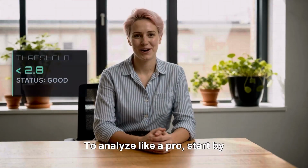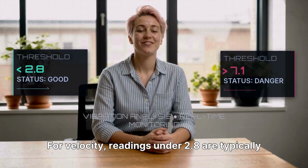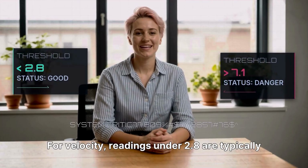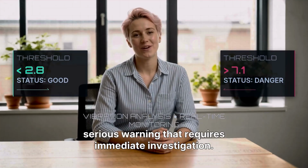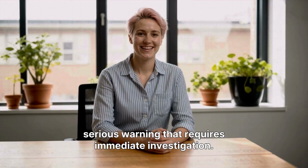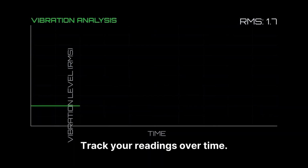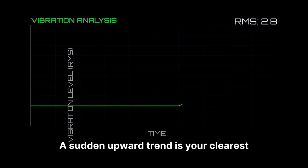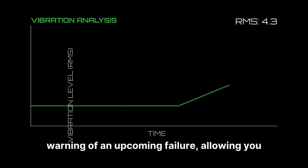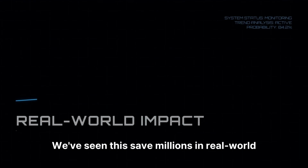To analyze like a pro, start by checking the overall RMS value. For velocity, readings under 2.8 are typically good, while anything over 7.1 is a serious warning that requires immediate investigation. Never analyze a single data point in isolation. Track your readings over time. A sudden upward trend is your clearest warning of an upcoming failure, allowing you to plan maintenance before a disaster occurs. We've seen this save millions in real-world settings.